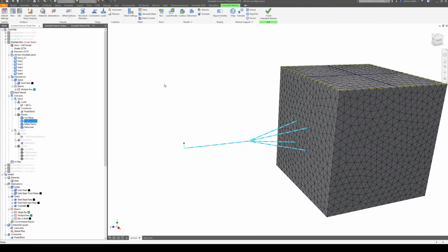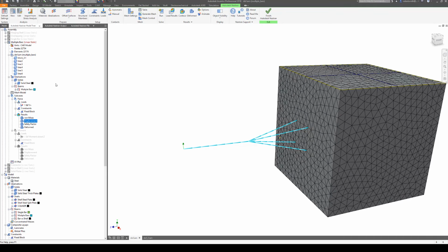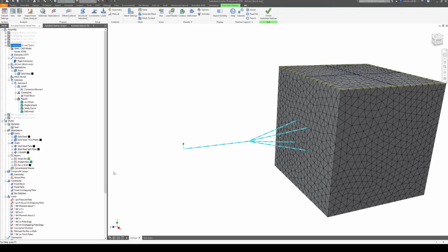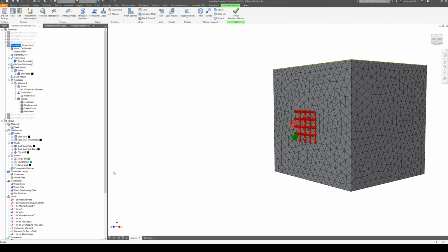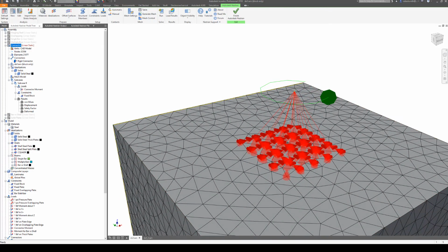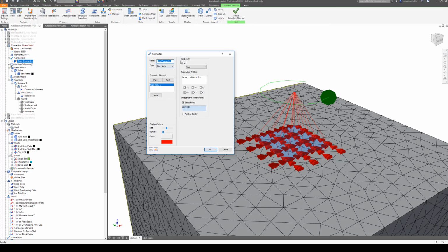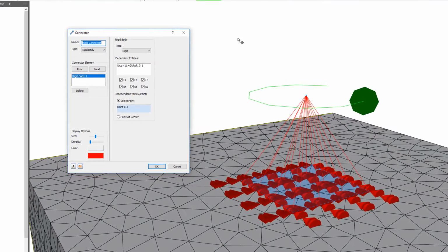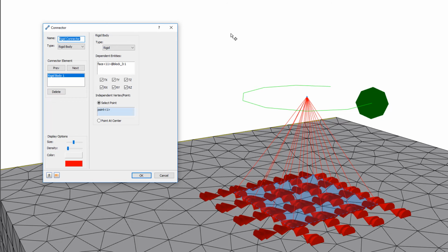Now, Nastran has other ways of dealing with this that they've built in for us. Specifically, you can use connectors. What I did in that last model was basically build a connector out of bar elements, but you don't have to do that. You can use a feature that's built into the software. Okay, this is a different type of structure altogether. It's not something that you have to pre-draw. You might have to have some geometry in there to pick locations. So for instance, I had a sketch point on one end and a split out surface on the other end, and Nastran built the elements in between those 2 locations for me.